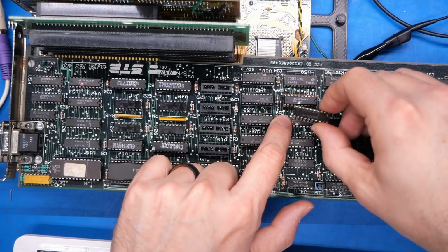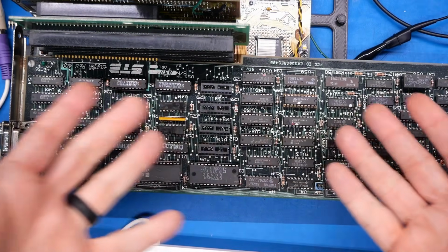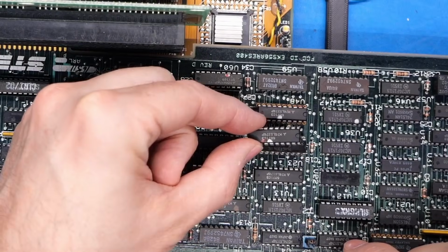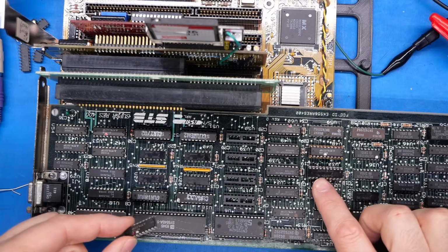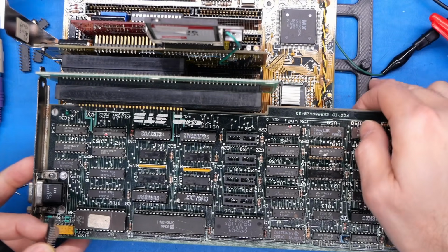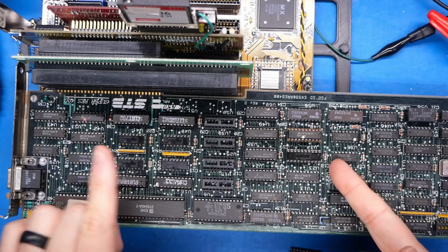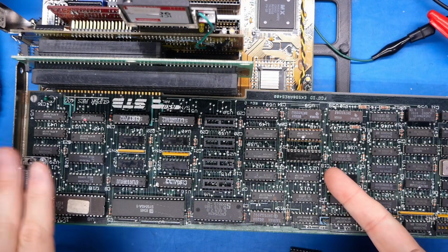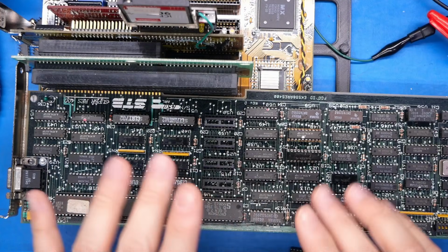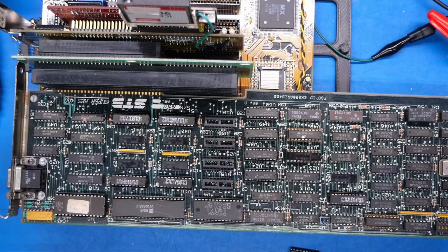And then we can try out this Fairchild part in here, see if that fixes it. Okay, the possibly bad chip has been removed, replaced with a socket and that Fairchild IC we were trying to use before. And for some suspense, let's not plug anything into the video output. Let's just scope those signals on here and see if that weird clock signal thing has gone away.